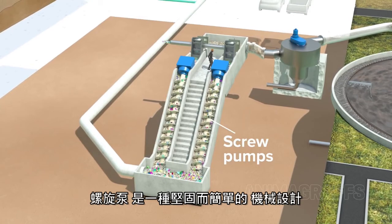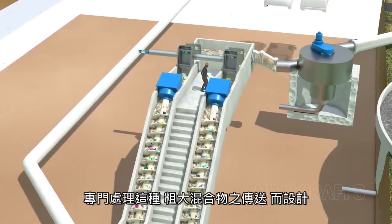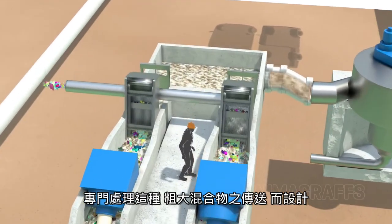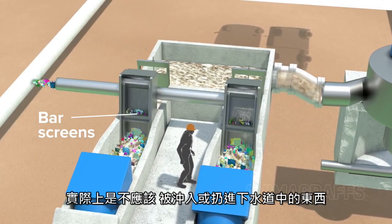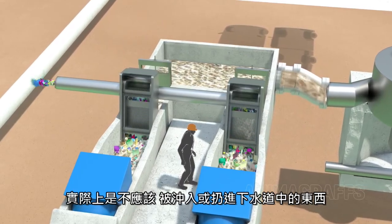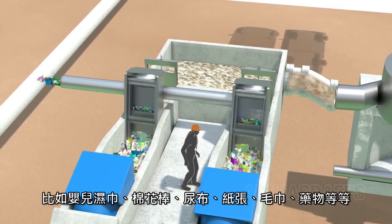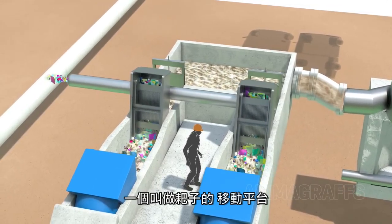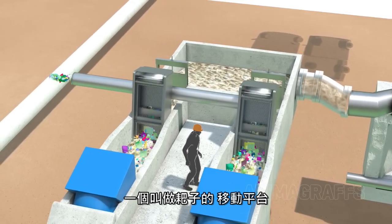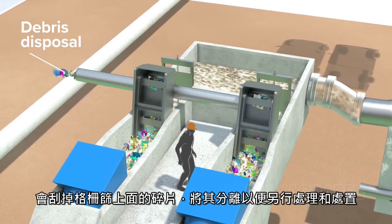Screw pumps are a rugged, mechanically simple design built to handle this coarse, incoming mixture. Bar screens trap debris, including literal tons of items that really shouldn't be flushed or sent down the drain, such as baby wipes, Q-tips, diapers, paper towels, medication, and so on. A moving platform called a rake scrapes the bars, removing the debris for separate processing and disposal.